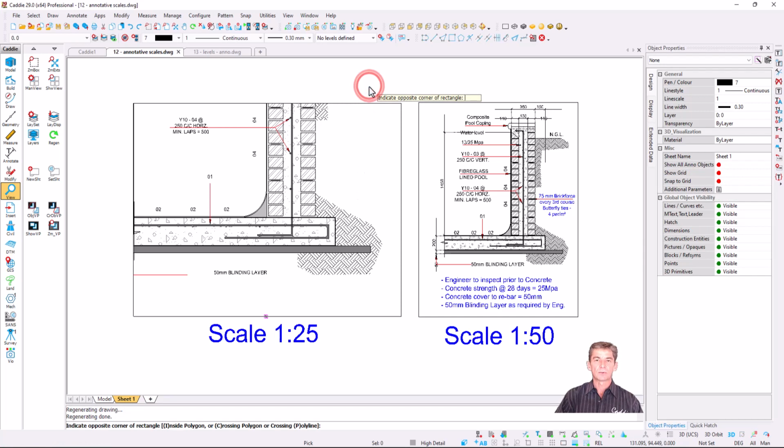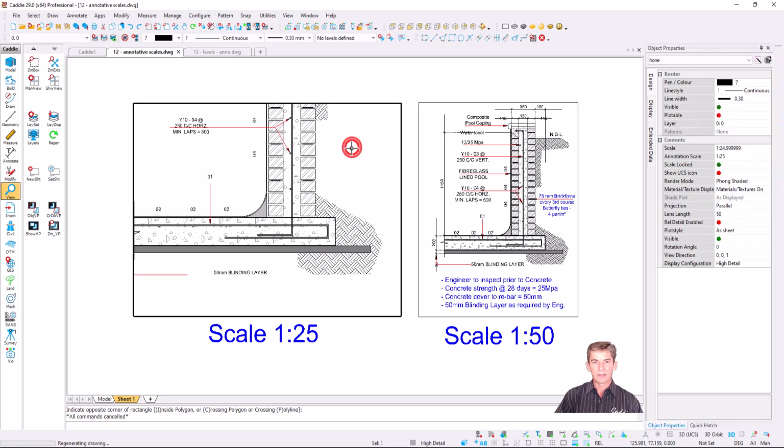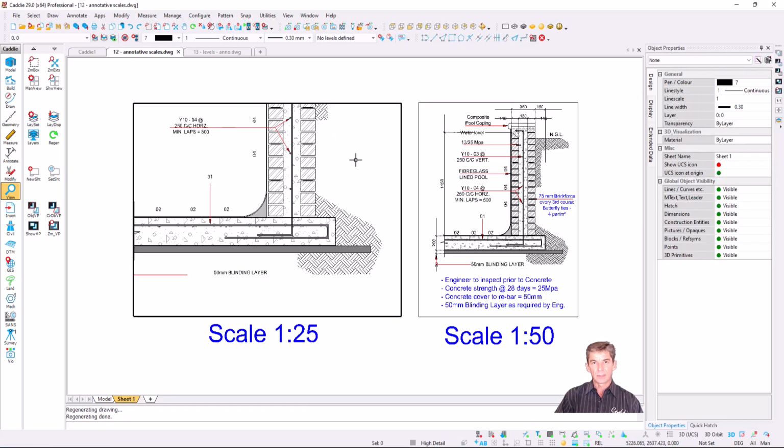If for some reason you would like to recall the annotation finishes in that viewport, all you have to do is double left click, and then now edit mode. At the bottom right hand side in your status bar, there's an option that says show all annotation finishes. Because it will not remember the 1:25, because you removed the 1:25, it will make use of, say, the 1:50.